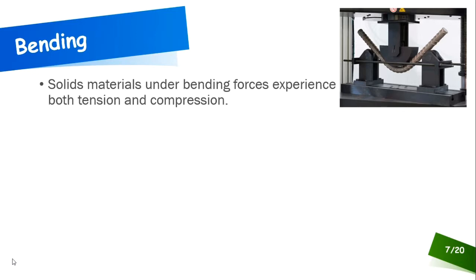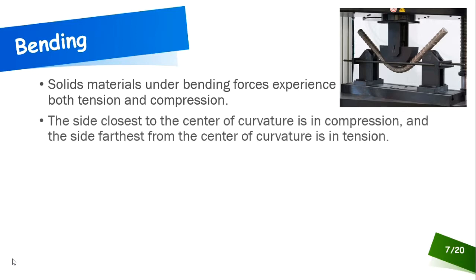When you press the go button, it pushes down with a certain amount of force, and you can pre-program it to have whatever force you want, applied at a certain rate. Eventually the bending strength of the material is exceeded, and there's a bend in the material.